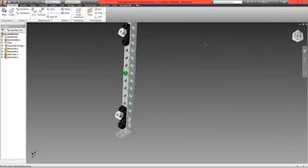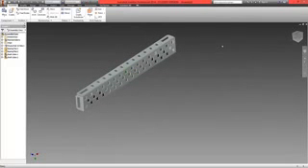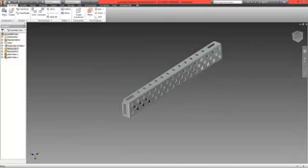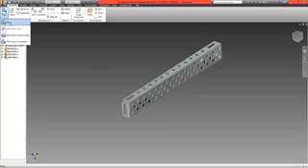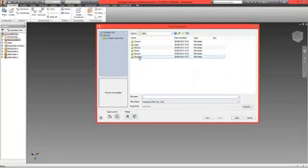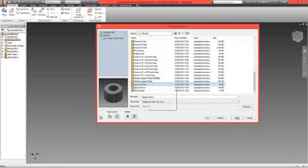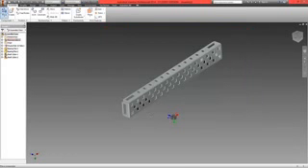Rotate your model around to the other side, and what we're going to do now is fit two spacers onto the holes where the shaft will go through before we place the wheels. Select Place, move up and into the Structure folder, and we're going to locate a 4.6mm spacer. Select Open, and then bring two of these parts in.